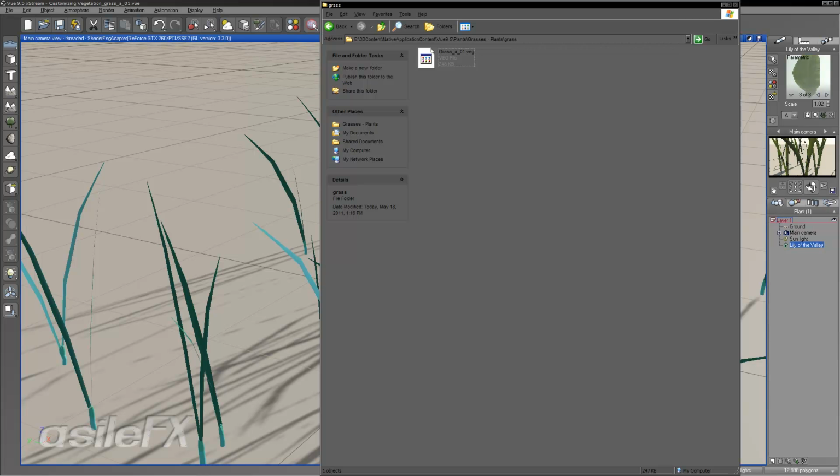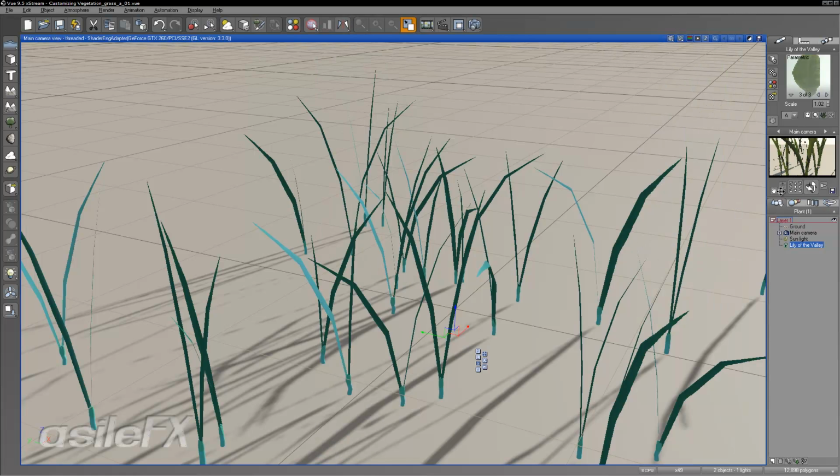With certain trees and other content, once you start saving outside the content directory, the file sizes can sometimes jump up to 20, 30 megabytes. And if you rewrite over it, it references itself within the other directory, and the file size becomes pretty much just the images, and that can cause issues between systems. So as long as we're saving within the content directory, we should be okay.